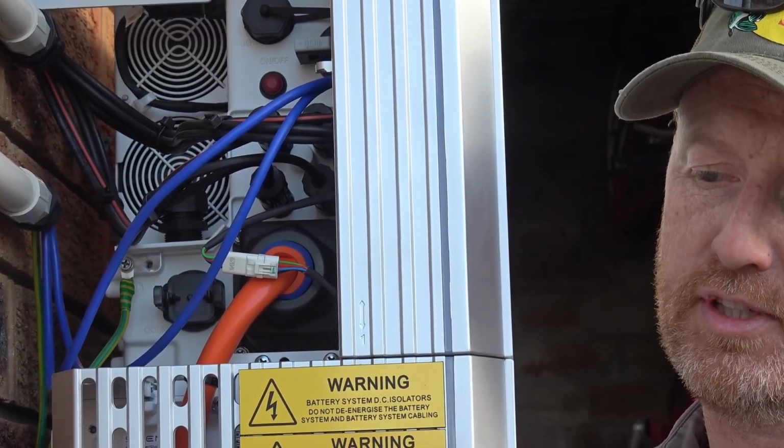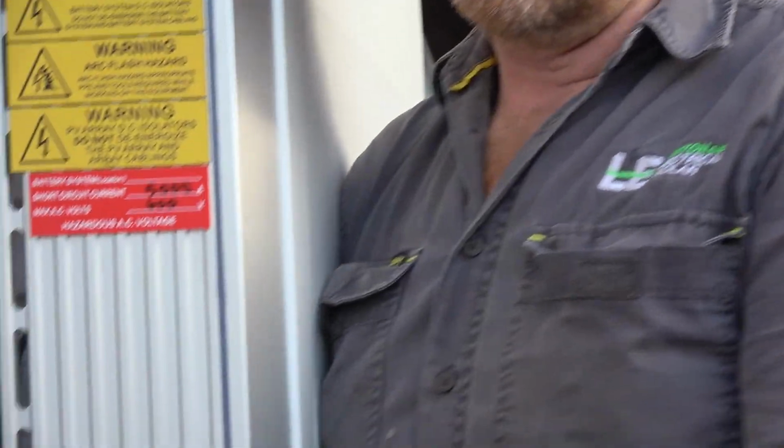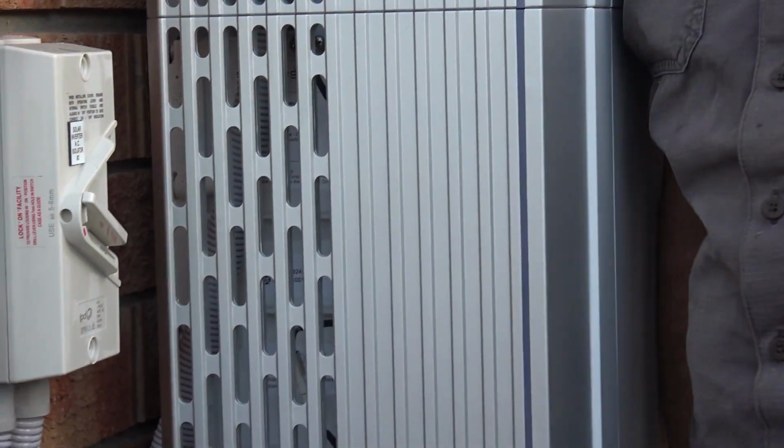Yep. But if you turn off the main switch grid, this side will still keep working. It'll power back up the circuits. And this switch? That is just an on-off switch for here. You have to have an isolator beside it when it's not beside the switchboard.